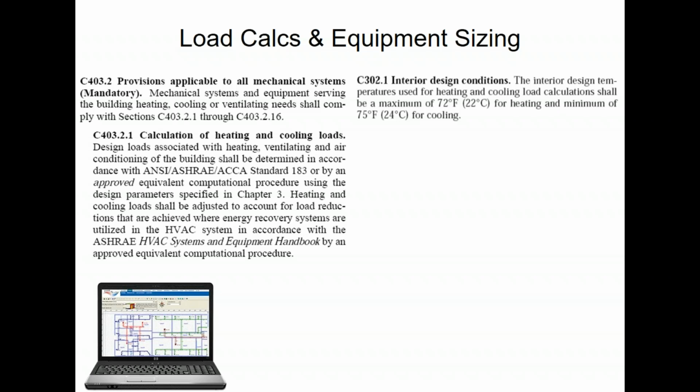I mention that because those two things are often things that get tweaked, if you will, in order to help somebody oversize. A lot of folks try to oversize for some unknown reason, which, as you know, oversizing just really hurts your dehumidification pretty bad. But they try to do it, and they do it by tweaking some of these inputs.